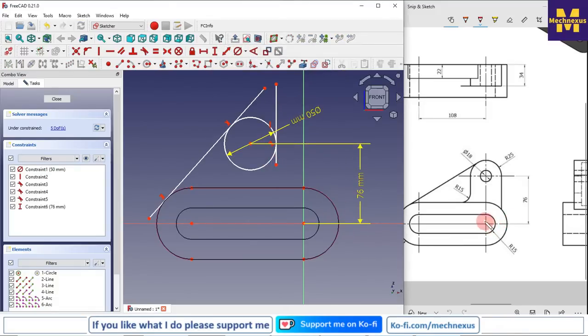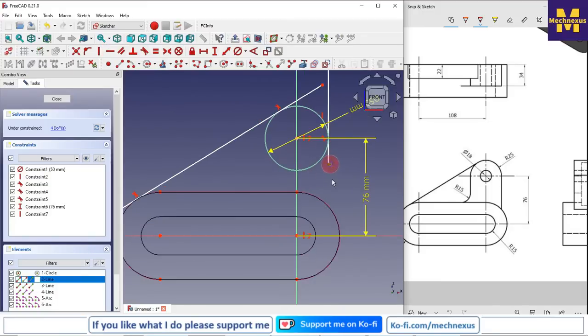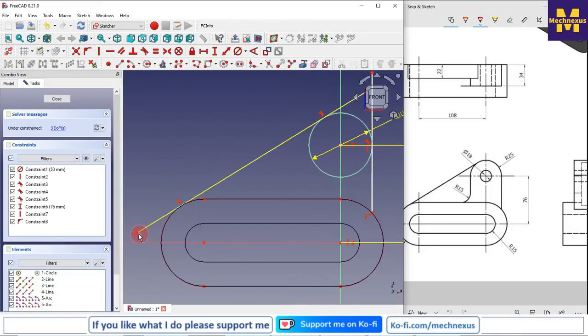And you can see here this center and this center is vertical, so I will select these 2 points and make it vertical. Now I select this point and this projected arc, make it the coincident relation. Similarly this point and this arc, coincident relation.